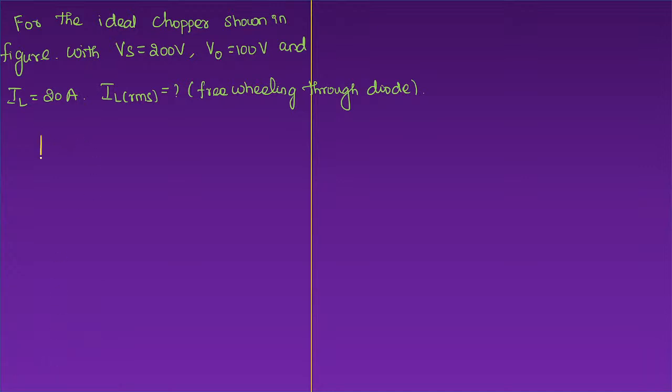So what they have taken is a DC source, with positive and negative polarity, connected in series with one inductor, and they kept one capacitor directly. Then they kept one switch here, then one diode, which they are calling the freewheeling diode.